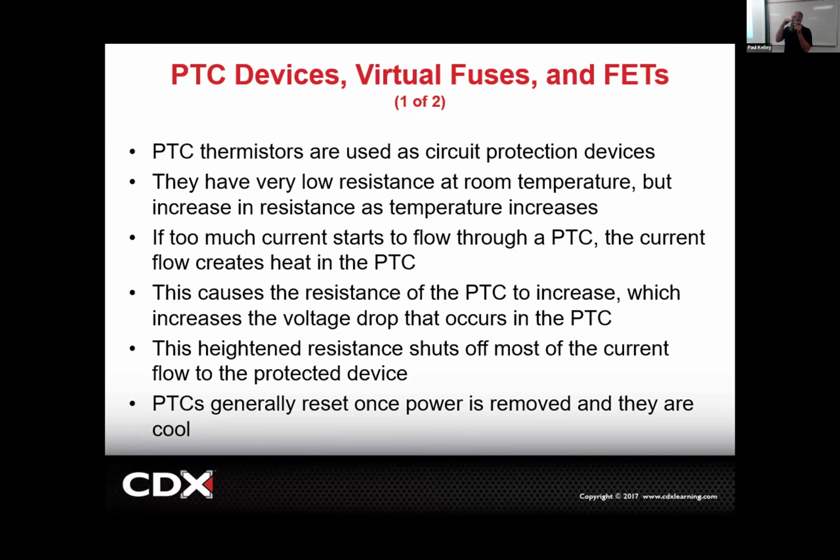Sometimes they'll actually build it into the component. You'll never find it because the electrical engineers design it inside the motor. The PTC can be very tiny, but pretty fun. And again, they reset themselves typically once power is removed. So if it's that power window, you're trying to run it, it won't work. You just have to let go of the switch and just walk away. That removes the power from it when you stop messing with the switch, and it'll reset.